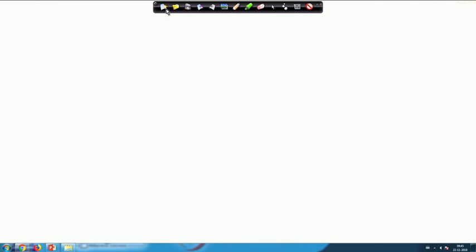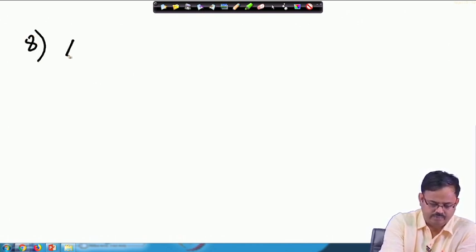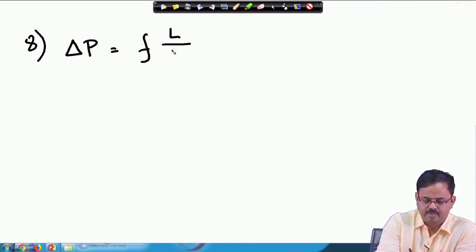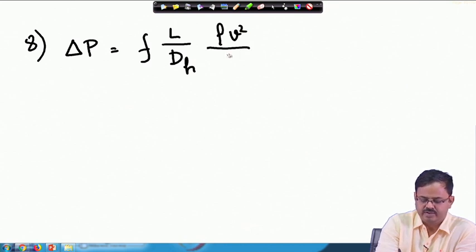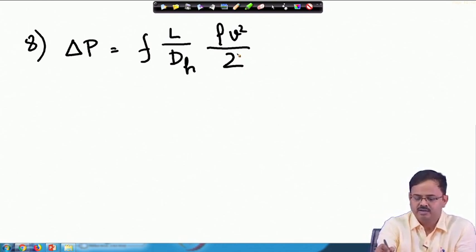Okay. The final thing was pressure drop. Delta P is f L by d_H times rho V squared by 2, you know everything. f we can find from the Moody chart. Okay.